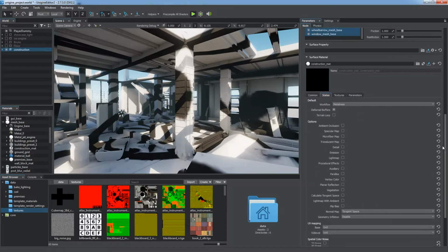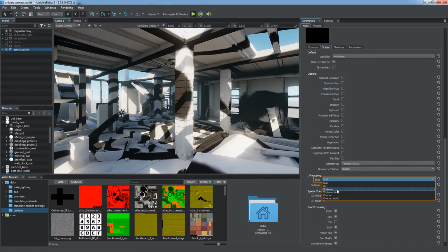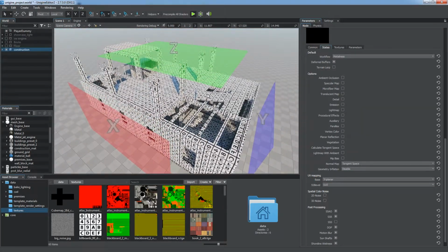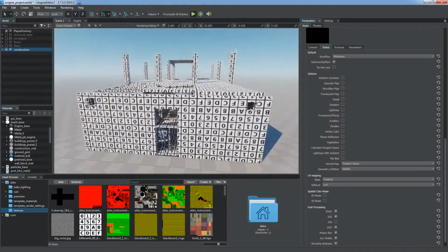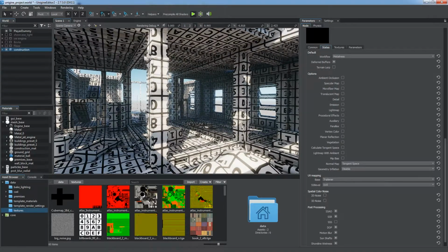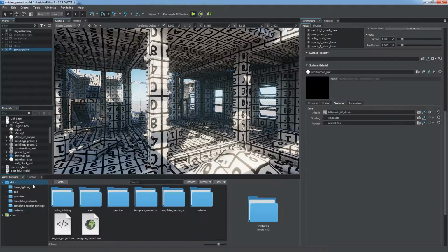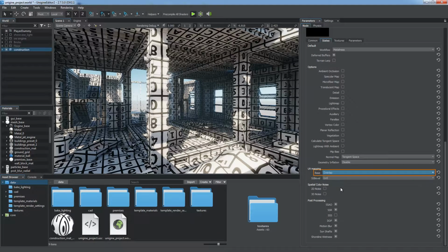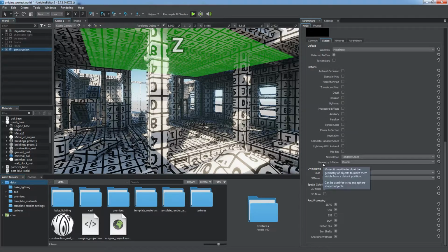Choose the Triplanar option of UV mapping in the material settings, and textures would be projected from 3 planar surfaces corresponding to the axis. If you deal with flat objects such as floor or ceiling which doesn't have vertical surfaces, Triplanar mapping is excessive. Let's select them, create a new child material for them, and switch to the overlap option to lighten the performance consumption. This option enables planar texture mapping atop the chosen surface.